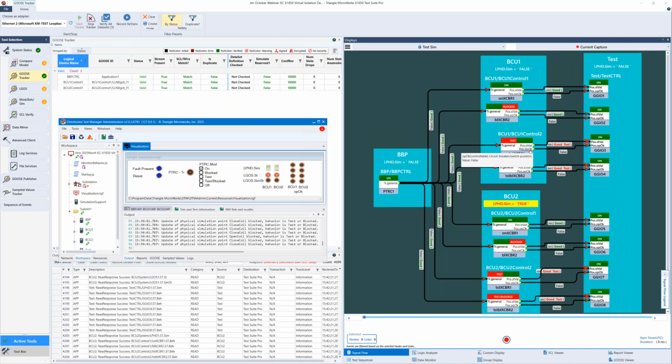So that can be used to verify the behavior without sending a trip. In principle, we can verify that the op OK goes to true when it receives a trip, but as it is blocked, the output should not change, so the position should not change. That's why we have this operate OK, and we are able to visualize it here as well.